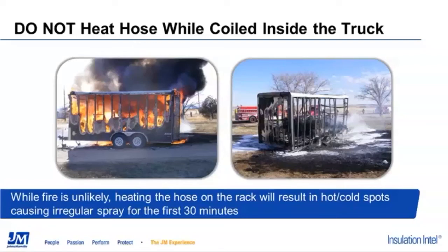And what happens in this scenario, we have a singular data point in the A side hose. Approximately 60 feet from the gun is where your thermocouple is. And whatever the temperature is of that singular data point, as far as your machine is concerned, that's the temperature across the entire thing. So when you have the hose coiled on the rack and it's stacked on top of itself, it acts as a heat accumulation. And while the spot where the thermocouple is might be in a 15 or 20 or a 5-degree environment, it thinks it's cold and keeps asking for heat.